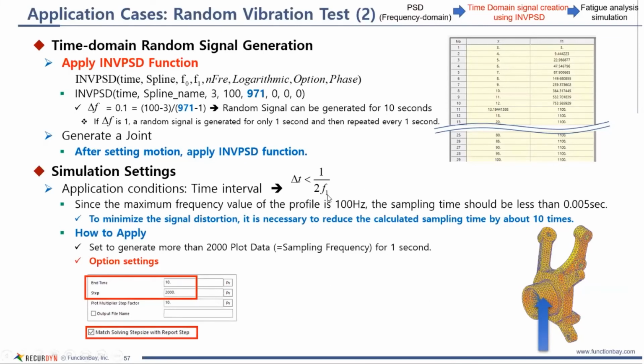Though I will mention here is if you're doing something like this, you need to make sure that your reporting interval is appropriate. So if your output frequency is too large, then you're going to be missing data. Basically, this is called the Nyquist. You need your reporting frequency to be less than this value to be sure that you're capturing all of the results.